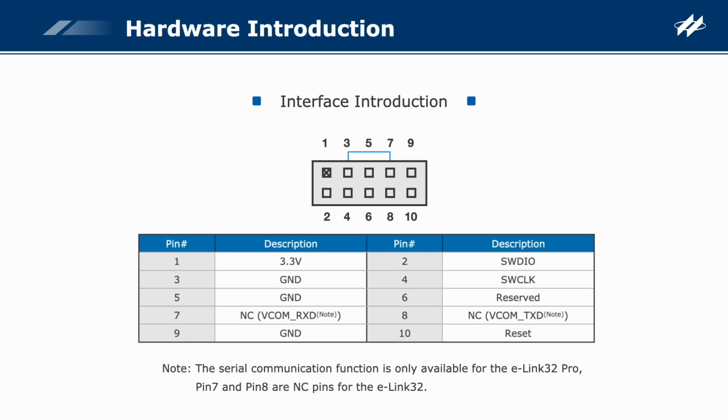The HT32 Pro supports 2 interface options, SWD and UART. The SWD interface is an ARM standard serial debug interface and supports the debug programming protocol for ARM core integrated hardware layer. The SWCLK, serial wire clock, and SWDIO, serial wire debug data input-output, pins are provided for programming and emulation. There is a USB virtual COM port for the HT32 Pro serial communication. Developers can select the proper interface according to their requirements.